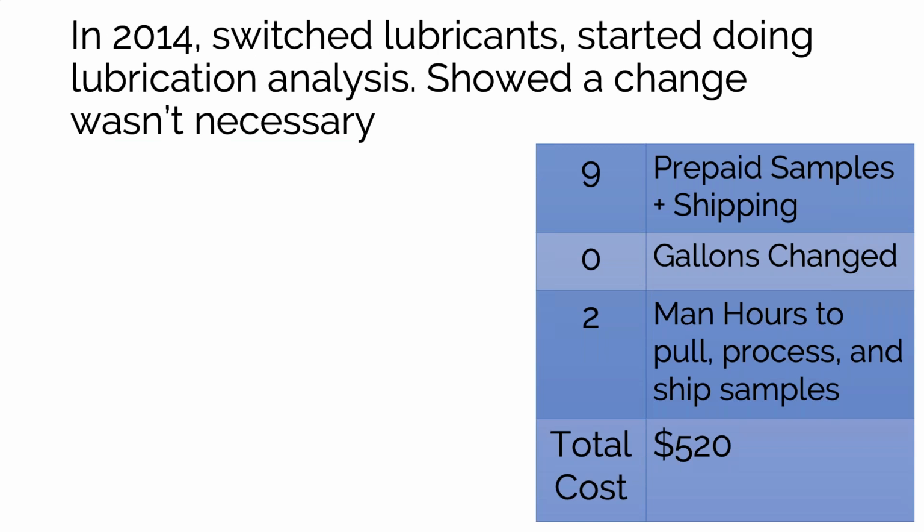In 2014, they did some investigation of lubricants, and they found one that was a food grade lubricant that had much better wear properties. And it was stated that this lubricant would last 4 years instead of the one that they had been using. So they decided to switch to that lubricant, and then they started doing lubrication analysis to make sure that it was going to last them beyond the 1 year period.